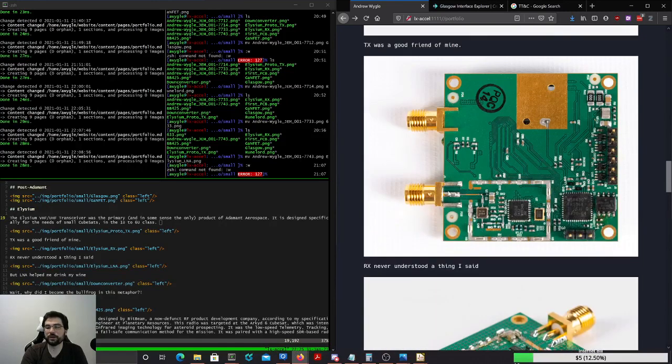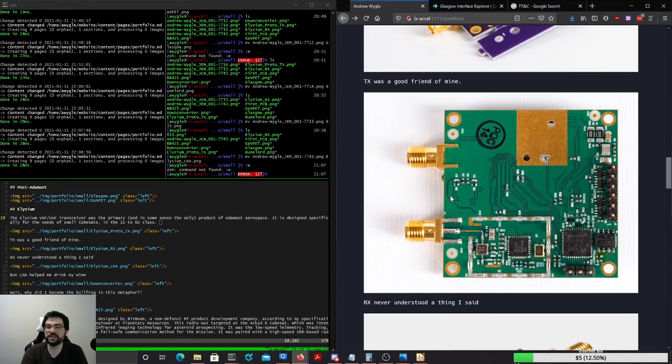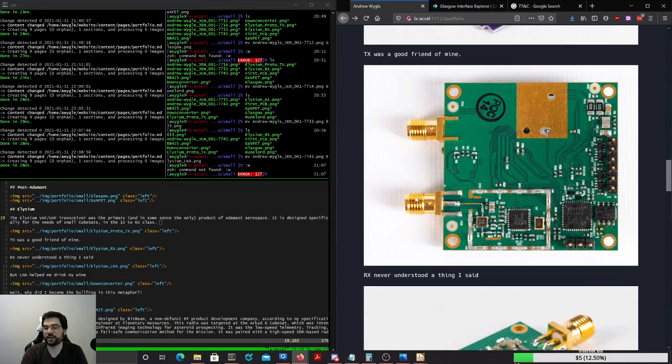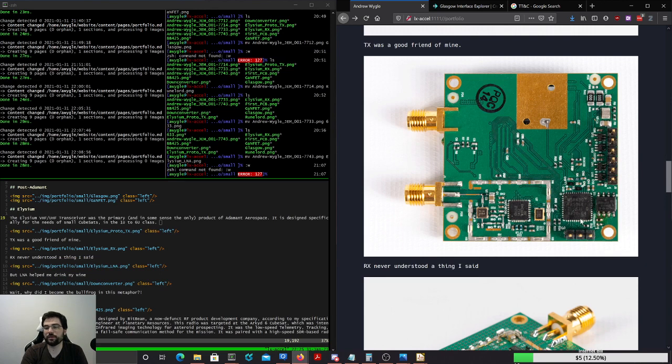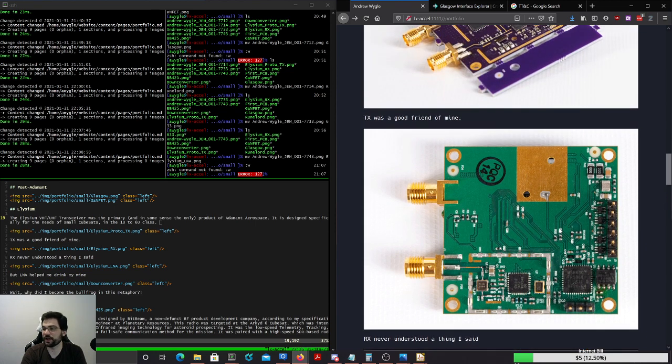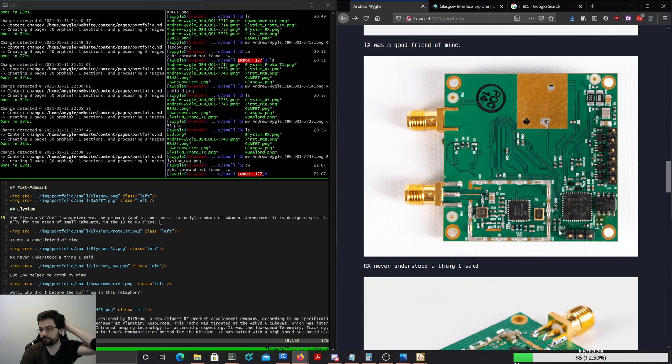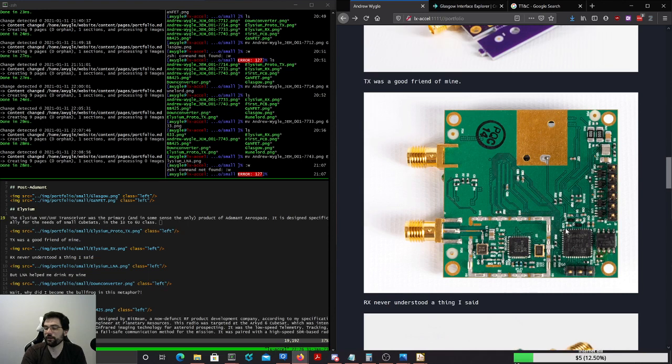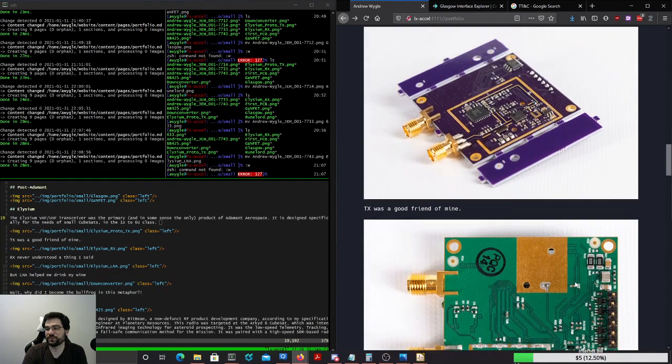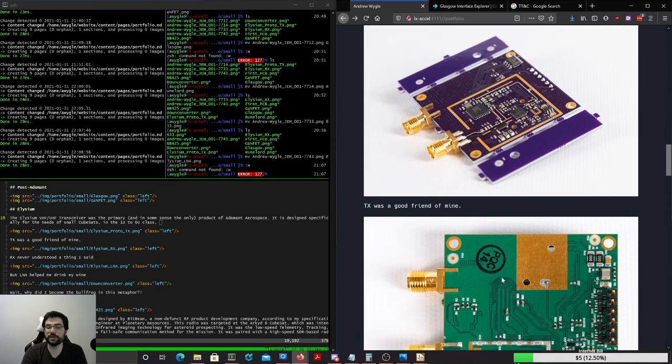And then the third one was that it should be, within reason, tolerant against radiation damage. And the way that worked was, this is an MSP430 that uses FRAM memory instead of SRAM and flash, or FeRAM if you prefer. And that stuff is really resistant to radiation damage. We actually stuck one of these in a medical accelerator, for nuclear medicine, for cancer patients. We rented one out and we stuck one of these MSP430s in it, and we hit it with a megarad of radiation before it died. We actually killed the test laptop long before we killed the MSP, and the test laptop was 3 feet away. So they're pretty sturdy. That's kind of the idea here, and it did meet all those design goals.